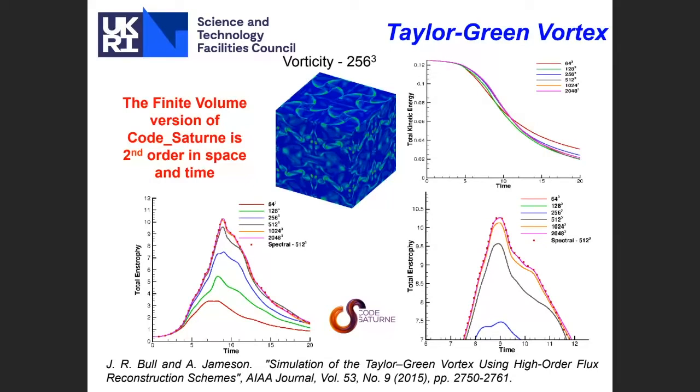So this was the scalability presentation and efficiency of the performance, but something that shouldn't be discarded is the accuracy of the code. A test case used for that is the Taylor Green Vortex, and the code has been tested from 64 cube to 2048 cube, which represents a 7 or 8 billion mesh.